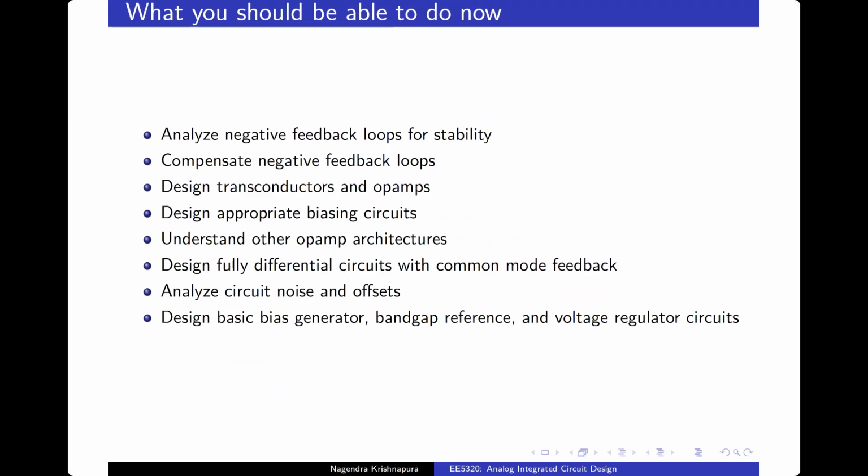That's why. But of course, I also mentioned this feed-forward works best when you have unity feedback around the op-amp. So that means that it has to be either a unity gain amplifier, of course, that's a very narrow range of applications, or more likely an integrator. You have R and C, there the feedback fraction is frequency dependent, but around the unity loop gain frequency, that C will be a short and you have unity feedback. Every active filter, or there is a large class of active filters which have this type of structure. So there the feed-forward op-amp is more power efficient compared to Miller op-amp.